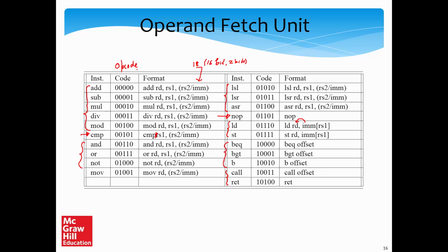So this 5-bit opcode uniquely identifies an instruction. The question is, why have we given the opcodes to the instructions the way that we have? So let's take a look at the branch instructions first. Essentially we need to look at decode complexity. If we take a look at the branch instructions, we'll see that all the branch instructions have been given an MSB of 1.